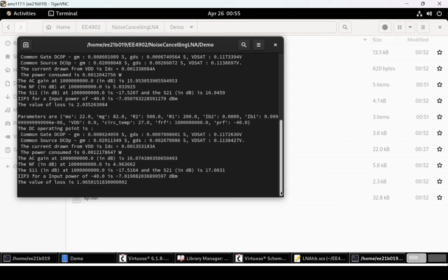Again, the loss has dropped significantly. Just for the sake of this video, I have considered only 10 iterations. The code can be run for several larger number of iterations, per se 100, and the best netlist can be chosen depending on constraints based on power dissipation, sensitivity, and process variations.